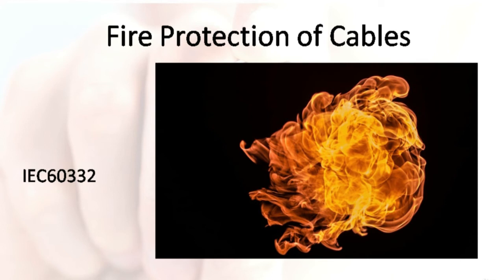The reason for this is that the halogens in the cable, although a flame retardant itself, release toxic fumes when combusted, which not only cause harm to the cable, but will also have a damaging effect on circuit boards, which also means that it may damage other equipment that may not be directly affected by the fire itself. And when I say other equipment, I mean your mining rigs.